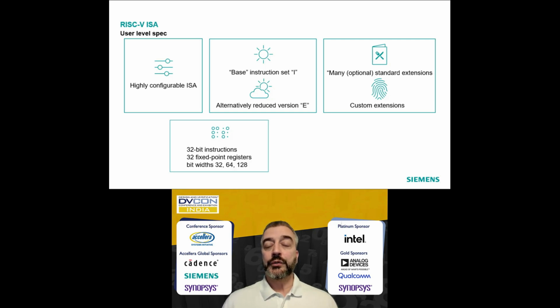And of course also the full claim to fame, the custom extensions, because RISC-V takes care to reserve instruction decoding space, register space, exceptions, and so on for custom extensions.